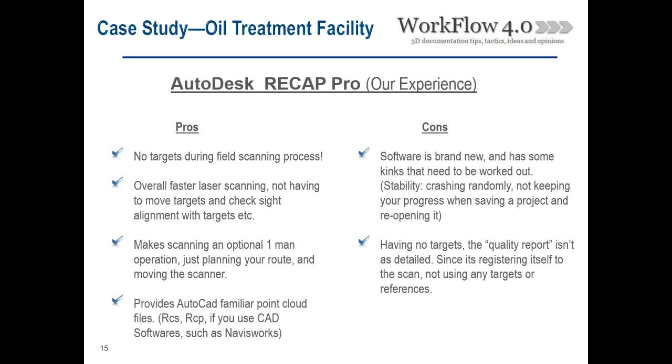There are some other things though. Like I said, it does overall faster laser scanning because you don't have to move targets and worry about line of sight and making sure you have enough targets. It does turn your field portion into a one-man job. You won't need two people if all you're doing is moving the scanner. You don't have to move your targets. You just plan your route and scan. It's very, very easy and efficient.